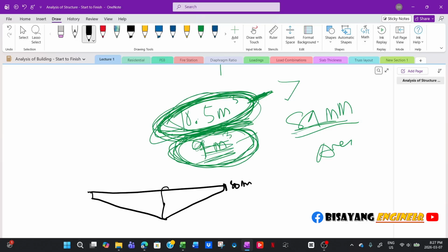Now, if that's the case, from pressure, which is gamma times height, so pressure of water is what? 62.4 pounds per cubic foot, then times whatever is the height. Let's just, this one is pounds per cubic foot, and then times the height here, divided by 12.